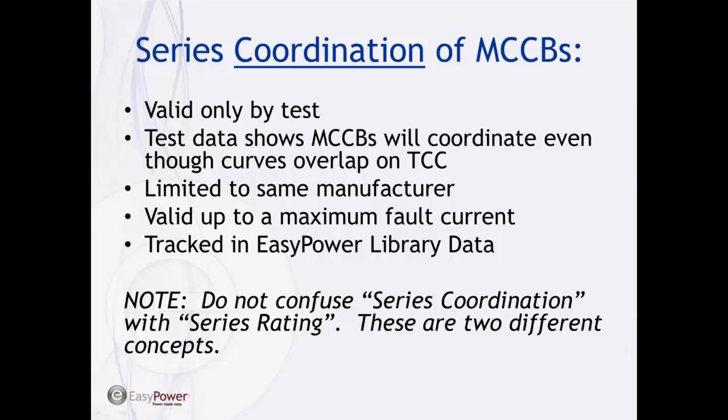Okay, now we're going to talk next about series ratings. That's a completely different concept than series coordination. So they sound similar, but they're completely different, so don't get those two confused. Series coordination relates to selective coordination between molded case breakers in series.